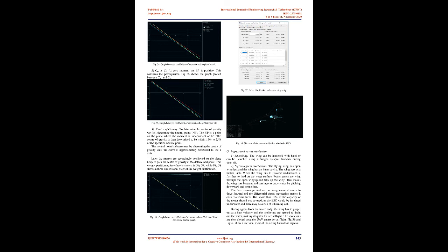There are multiple types of polars and analysis methods to choose from in order to perform a performance analysis. Figs. 20 and 21 show the interface for polar types and analysis methods. Polar types: Type 1, fixed speed; Type 2, fixed lift; Type 3, fixed AOA; Type 4, beta range. Analysis methods: LLT, wing only, horseshoe vortex VLM1, ring vortex VLM2, and 3D panels. Based on our requirements, the type of analysis being performed, and the results needed, the following settings were chosen: Type 2, ring vortex VLM2.